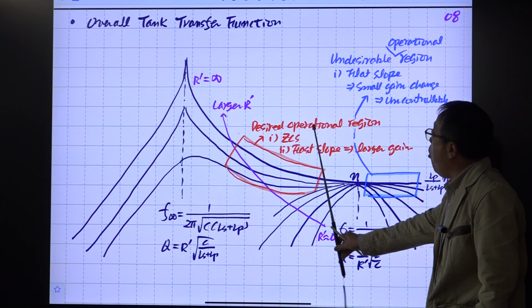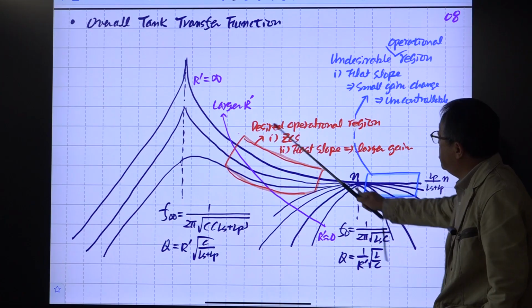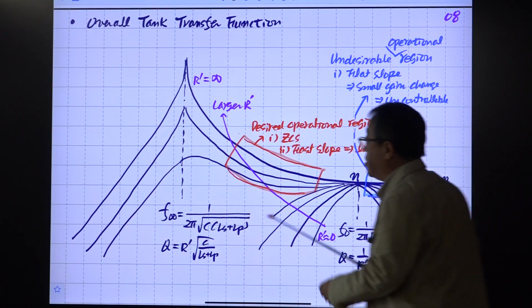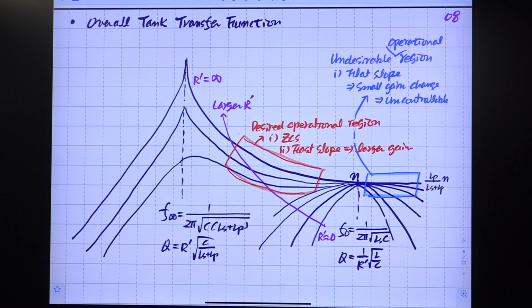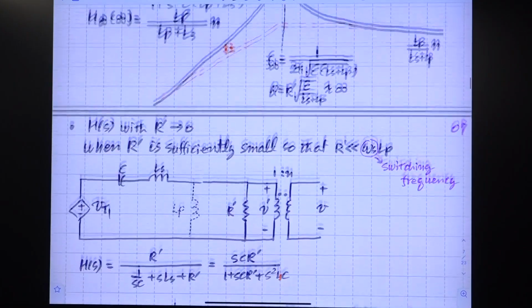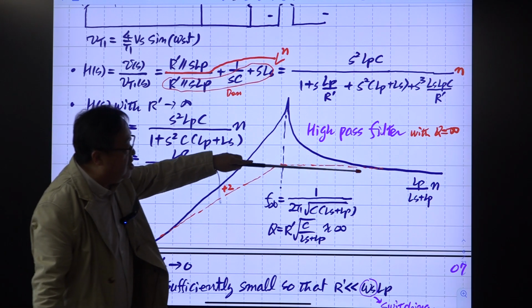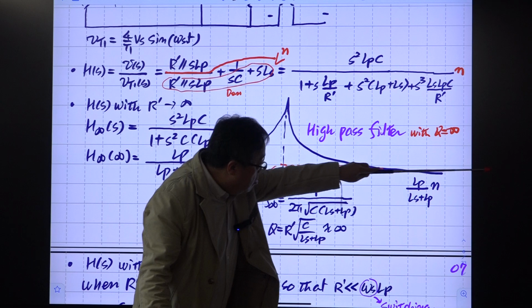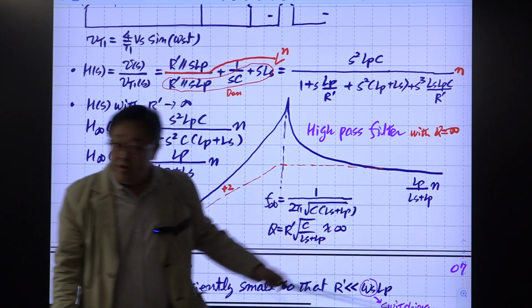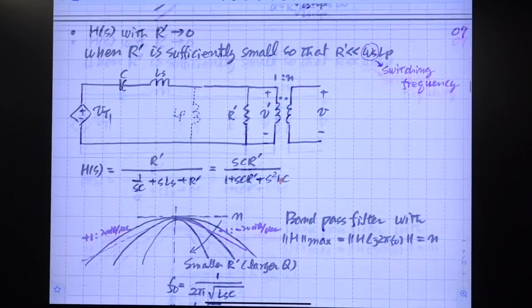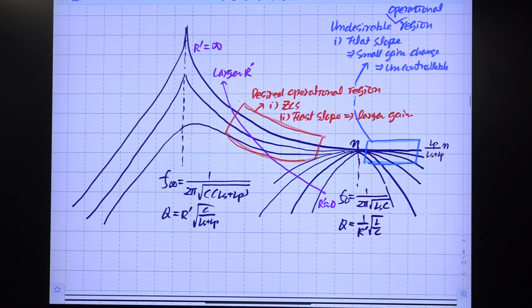Okay? If you go to very high frequencies, this is the high frequency asymptote of this thing. I forgot to mention this. That is very easy, because the high frequency asymptote is just the ratio of this coefficient, which is this. So at very high frequencies, the magnitude curve converges to this value. By combining those two curves, we have these characteristics, right?